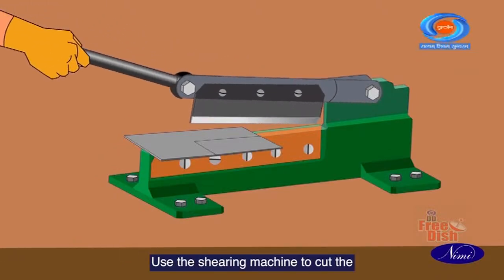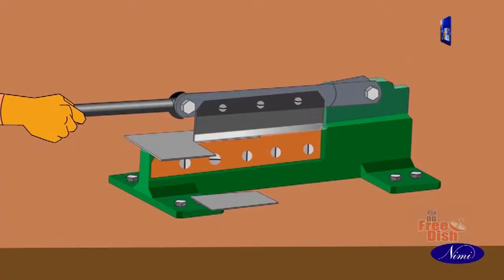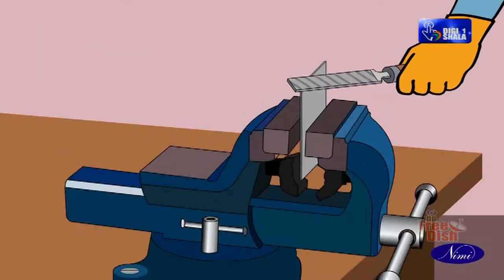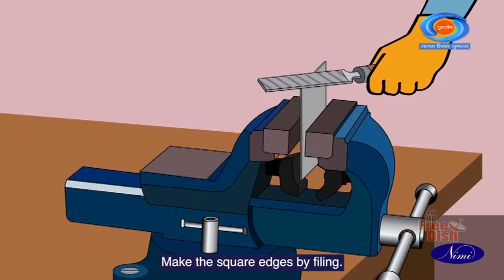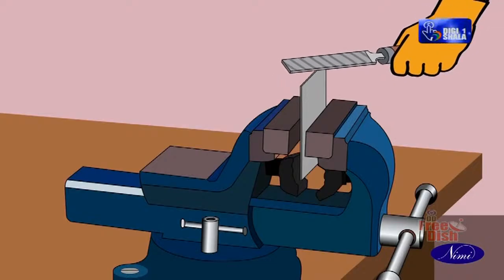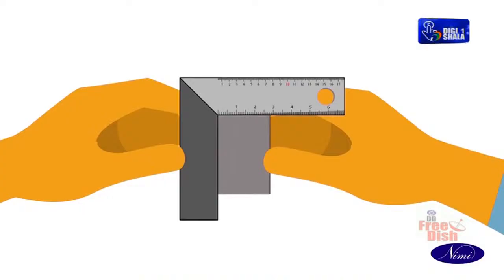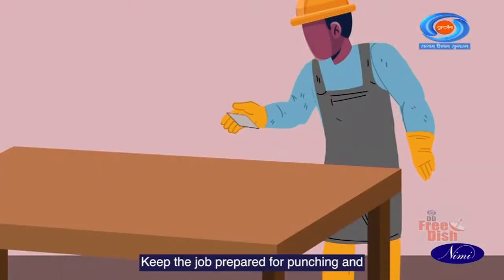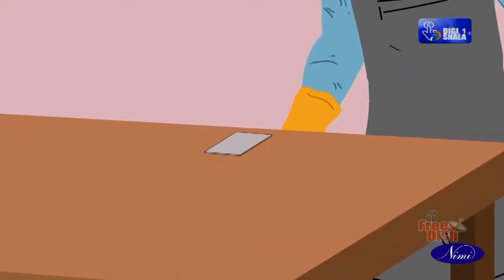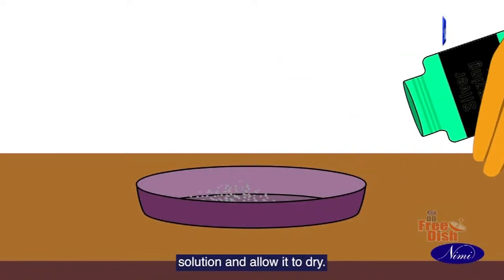Use the shearing machine to cut the job piece according to the marked size. Check the edges for smoothness. Make the square edges by filing. Check the squareness using tri-square. Keep the job prepared for punching and marking after testing the squareness. Apply copper sulfate or chalk powder solution and allow it to dry.